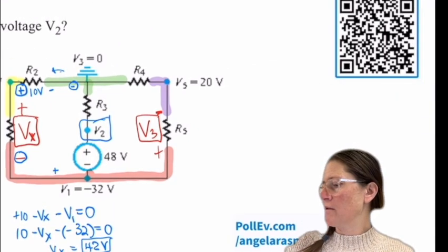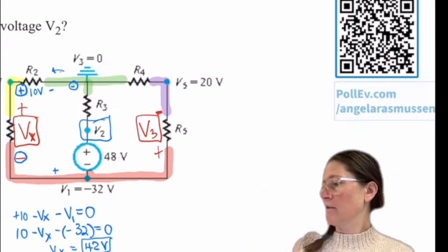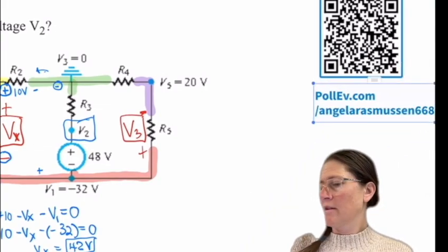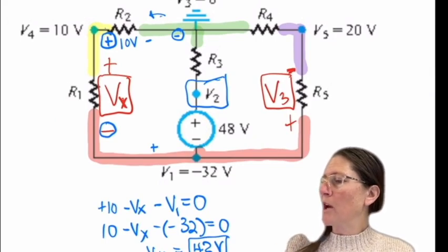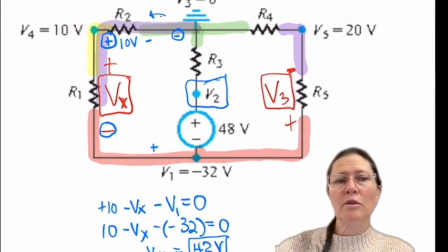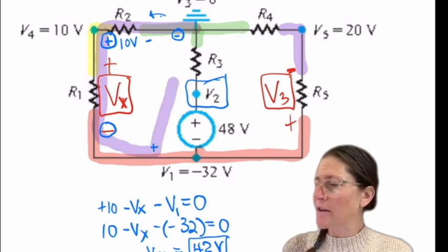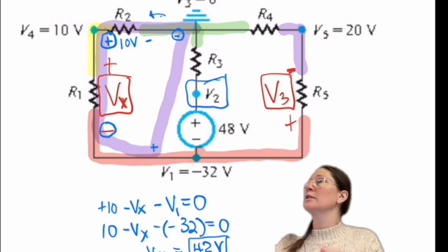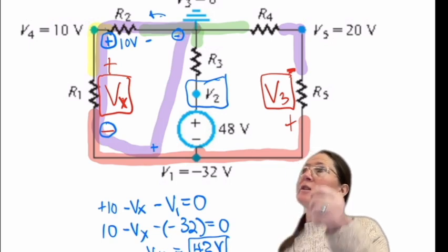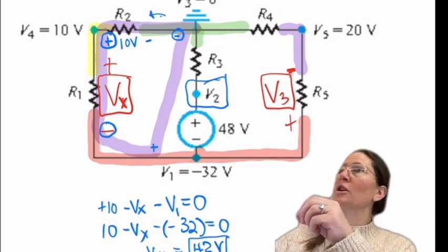Questions about that? Yes, go ahead. Is that a complete loop? How are you getting 0? So my pathway is going through R2, through Vx, and then this volt, that's like through the multimeter, even though it's not drawn. So that's a physical connection, it's just not drawn.